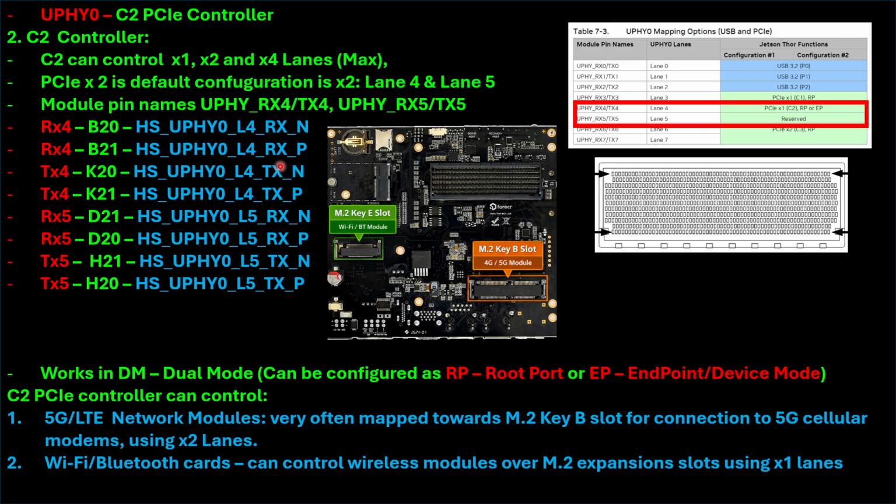These configure the signals which are going through the PCIe lanes. So the standard setup is receiving and transmission for one lane, and that's actually everywhere, either PCIe or NVLink. There's always transmission and receive, also in Ethernet and so on. Then we have the same story for lane 5.